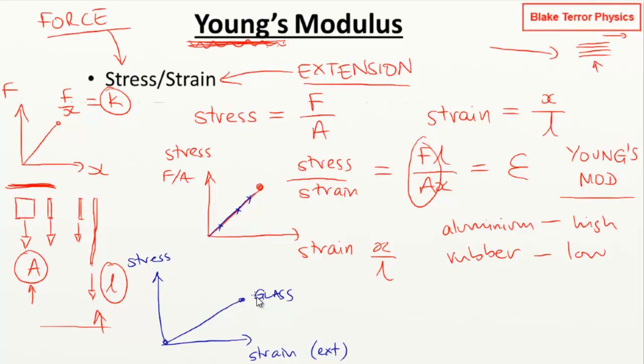You don't get this inelastic deformation bit which is going to happen somewhere else. You've got a tiny amount of give and then it's going to snap because it's brittle. So this is what you get with the brittle stress-strain graphs, and sometimes you get the arrows on it showing that they're loading and unloading along the same graph. You've got a similar thing with a higher Young's modulus if you've got something like cast iron. So that's what happens with these brittle materials.